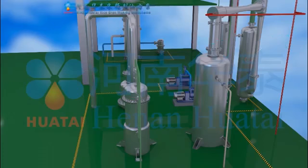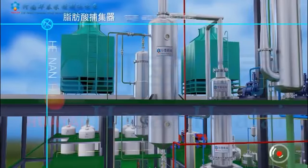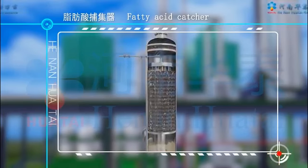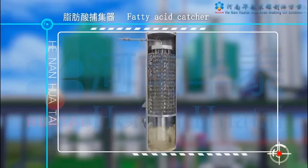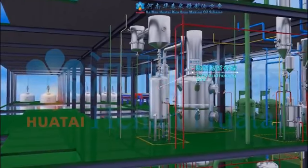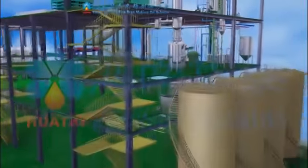The fatty acid gas from the deacidification tower and the deacidification deodorization tower is conveyed to the fatty acid catcher. After centrifugal separation, the fatty acid liquid is recovered from the fatty acid recovery system. Fatty acid liquid is recovered to the temporary starter tank. Through the fatty acid pump, it is sent to the outdoor fatty acid tank.